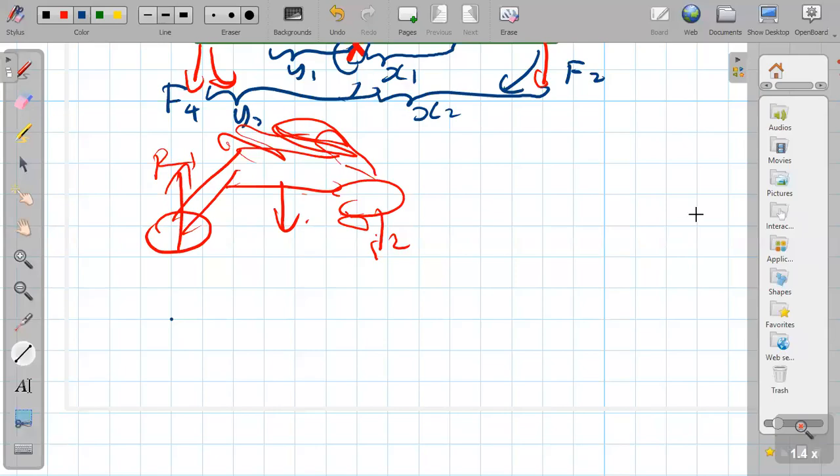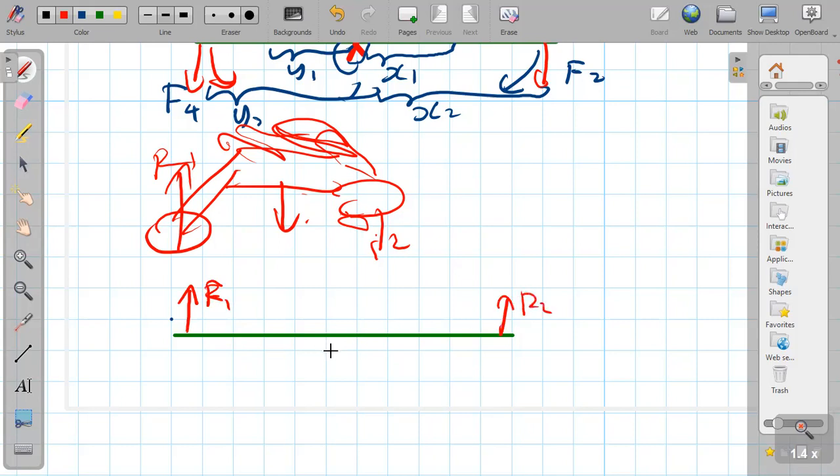The best thing is don't draw any person or motorbike or any system, or whether it is a plane. Don't draw. Only consider this whole system as a straight line. Mark all the forces like R1, R2, and mg. Understand? And from the person, it's like simple mg.